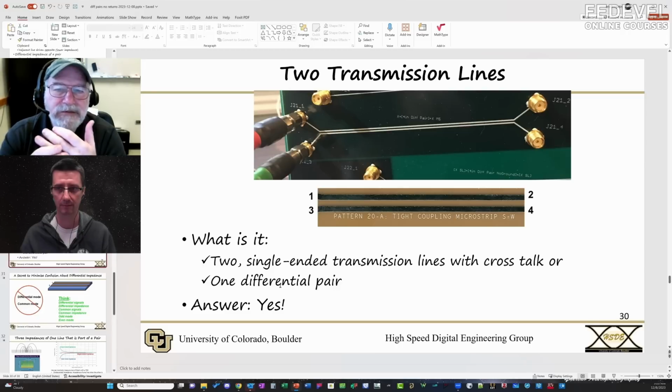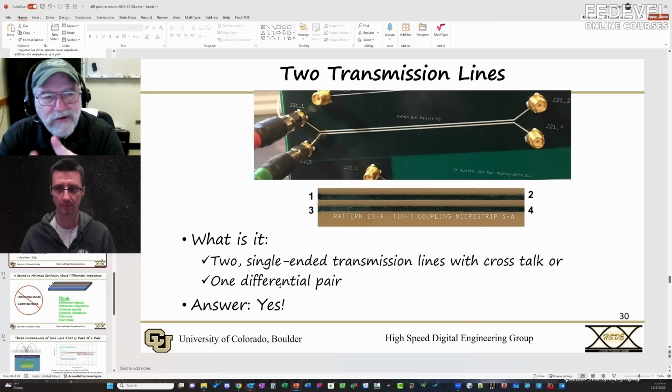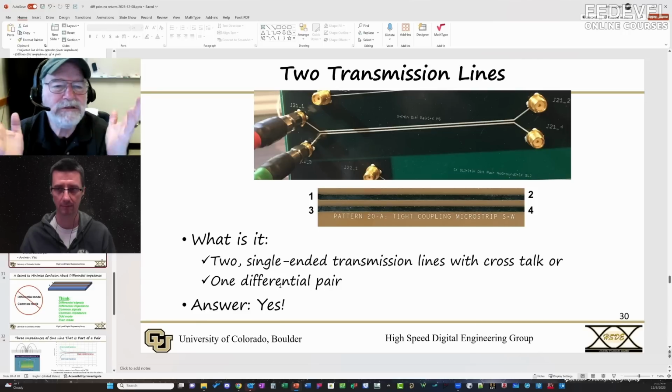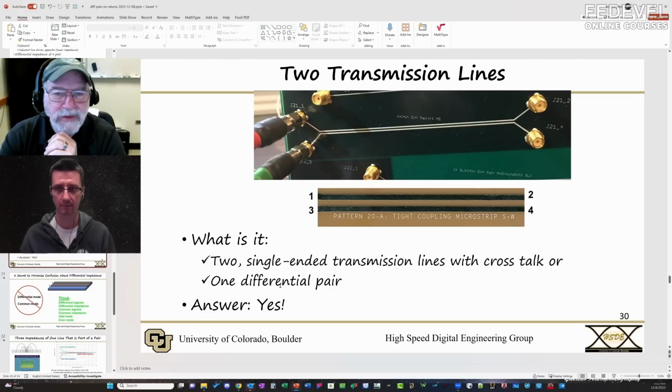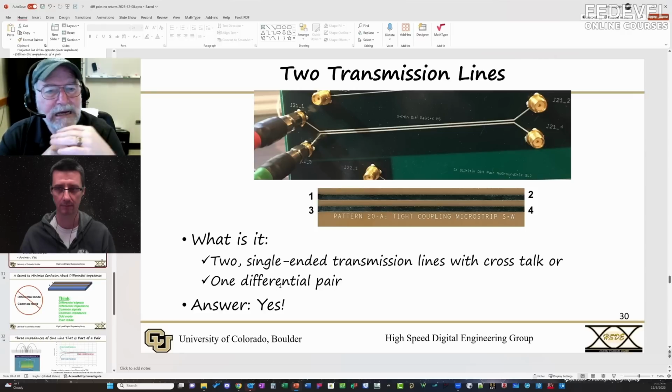And if you use unshielded twisted pair for Ethernet, and I'm going to show you an example here in a minute, if you drive it with a pure differential signal, there is no common signal. You don't fail EMI rated emissions. But if you have any common signal on that external unshielded twisted pair, 99% of the time, that's the source of failures for FCC.